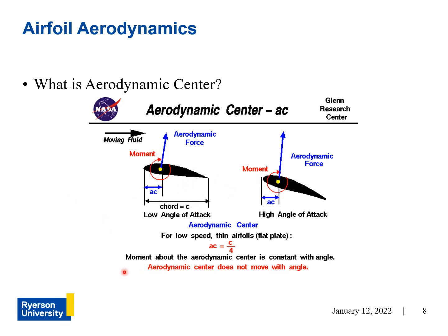Again, as I explained previously, symmetric airfoils have a pitching moment equal to 0 at the aerodynamic center, because of the same phenomenon of the flow being equal at the top and the bottom at 0 angle of attack, so it wouldn't produce any moment.